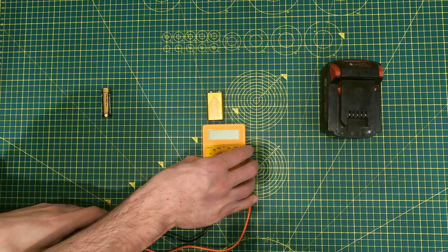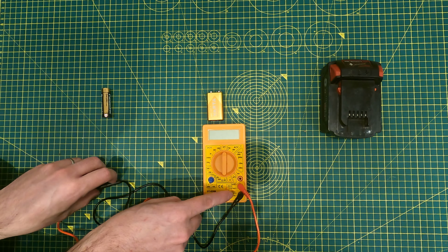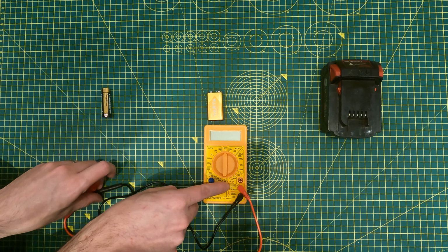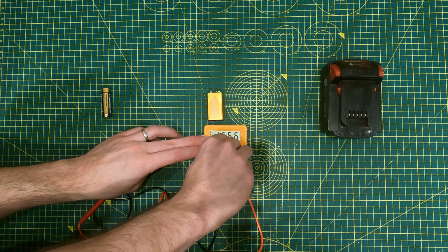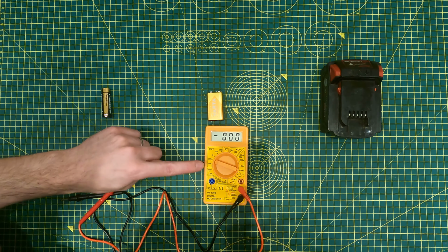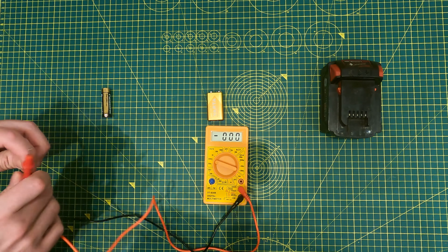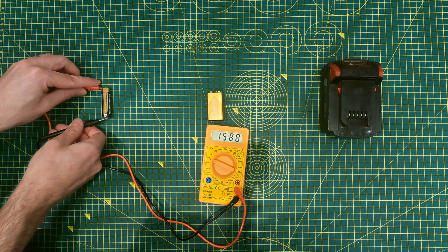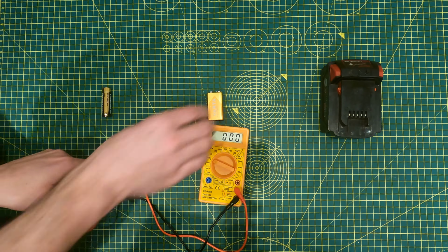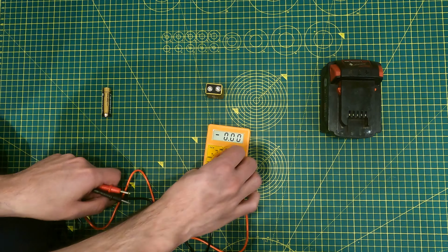Okay, let's go ahead and take a measurement of these batteries now, and remember to have the black probe in the COM terminal and the red probe in the multifunctional terminal. So, like I say, we find our value above 0.2 and below 2 volts for the 1.5 volt battery, and then you just test it over the anode and the cathode. We've got 1.6 volts.